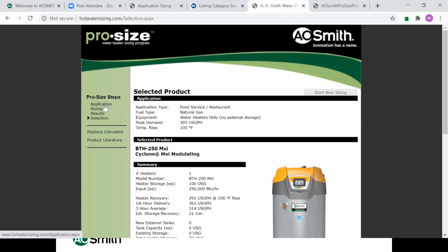It was all across America back in like the 70s or 80s, which obviously fixture units have changed, but they've not done a large sample to understand how demand has changed. So for now, this is still our best guess until, if ASHRAE or whoever decides to go do another Hunter's curve type sample. Until then, our fixture units that we have are the fixture units that we have, and we've got to design with them.